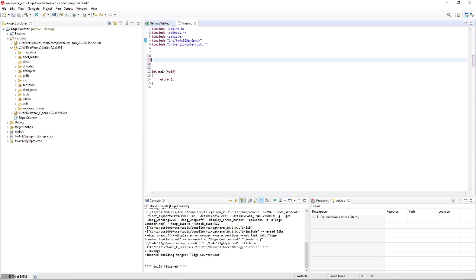So what we're doing today is we're going to write a very simple program that just tracks the number of times switch 1 is pressed on the TIVA, and it's going to display the number of times it's been pressed on some external LEDs we have rigged up on our breadboard. We're going to count up to F in hex. We have 4 LEDs, and they will represent each of the bits of the count. And we're going to count them on an interrupt, which won't look very complicated for this, but it will be essential for later stages of the project.